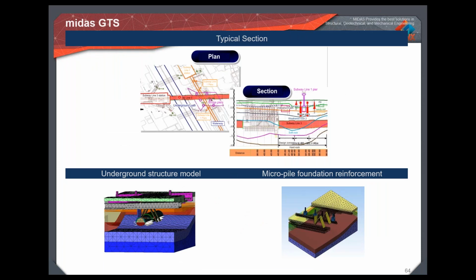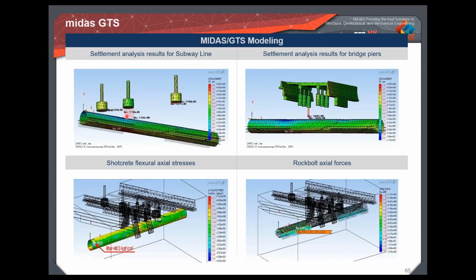This is a subwell, and when they needed to dig the tunnel, they found the bridge pier is facing a differential settlement. You can find this is my displacement. This is a pile cap basically, and here you're having more displacement at the other end, which is not feasible. So they went for shotcrete, the thickness of shotcrete has been increased and the rock bolts have been provided even higher, and they found that this differential settlement is not arising now, and that the complete model is safe.